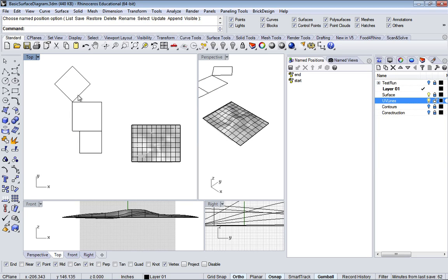You got to make sure that those are selected so it knows what geometry it wants to record the positions for. Okay, so this is great. Like if you're going to do a program showing how things shuffle around the site, or if you're going to show when you've built this great model that has the windows and the walls and all the structure, what this allows you to do is take all those components and do an exploded view of that. So taking all of these things and showing it all kind of separated out and kind of flying together, without losing the finished model.